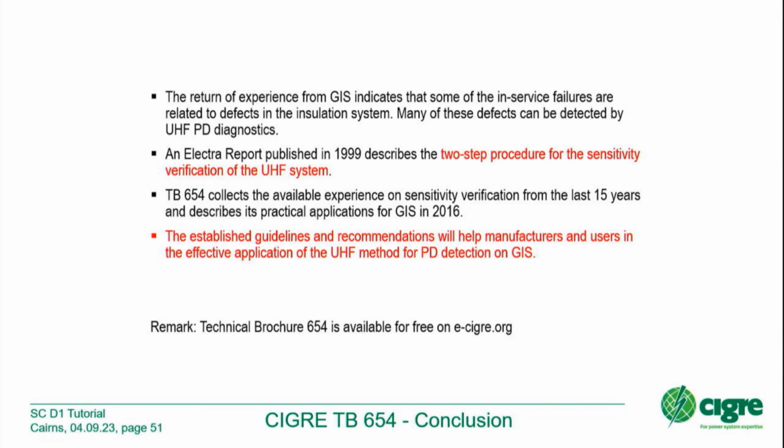No, for the step 1, you have a very small test time because you only want to see the magnitude of the artificial pulse. So at that step 1, we never discuss lengths or connection to cable or transformer. That's the reason why normally they use two sensors very close to each other and to forget what is coming left and right. So at the end, the main thing here is the impedance of the GIS. The impedance design, which is related to the impedance, the type and size of the sensor and the equipment for measuring, which is most important because we had some instruments from the 1990s, continuous improvement. So today's equipment is not, let's say, comparable to 100% with the instruments from 1990. Yeah. So also when you change the instrument, you have to repeat the test.